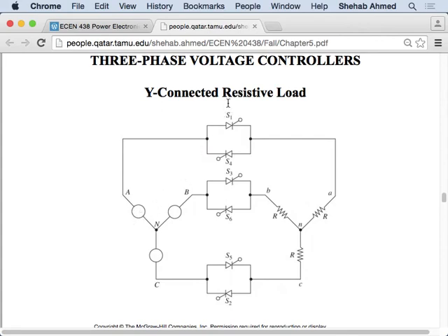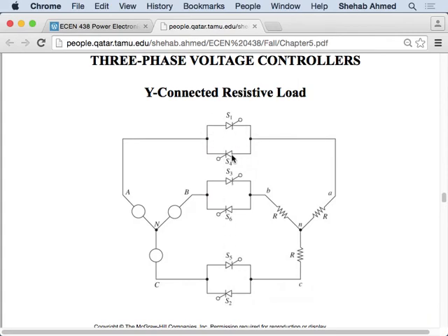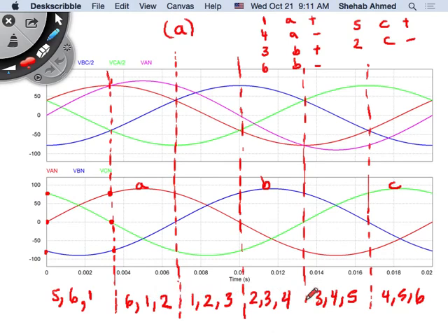Because if all of these are diodes, meaning all of these combinations of back-to-back diodes look like just wires, right? In that case, I have phase A connected to load A, and then these two neutral points connected. I can draw the equivalent single phase circuit outside, right? So if the switches are conducting in this fashion for this whole interval, then I have VAN at the output. VAN on phase A. VAN is this pink waveform.